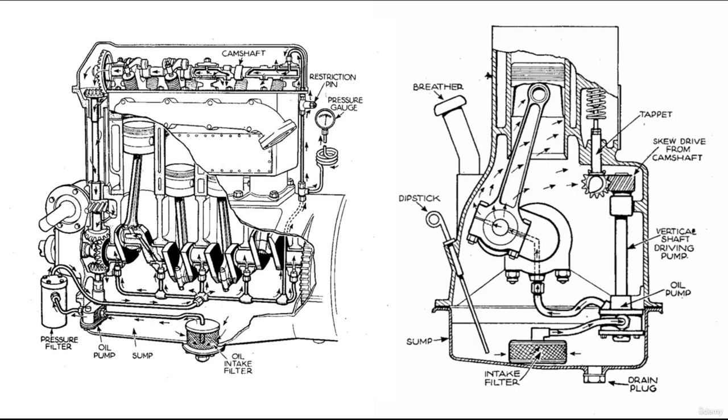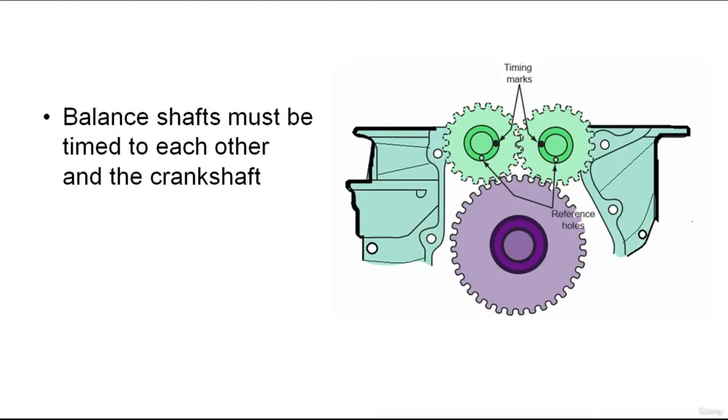The increased clearances reduce the resistance to oil flow and consequently increase the volume of oil circulating through the engine. This decreased resistance and increased volume lower the pressure of the oil. The ability of an oil pump to deliver more than the required volume of oil is a safety measure to ensure lubrication of vital parts as the engine wears.